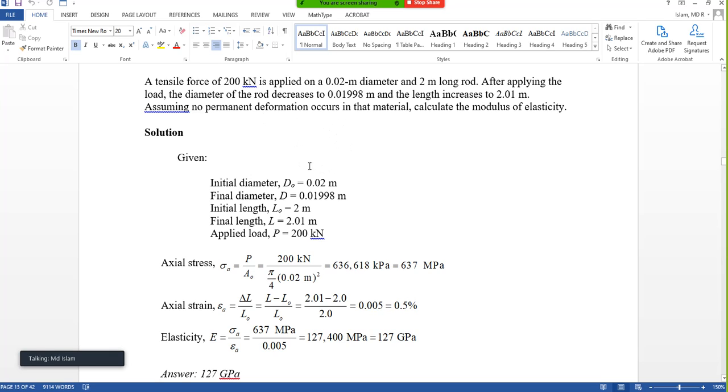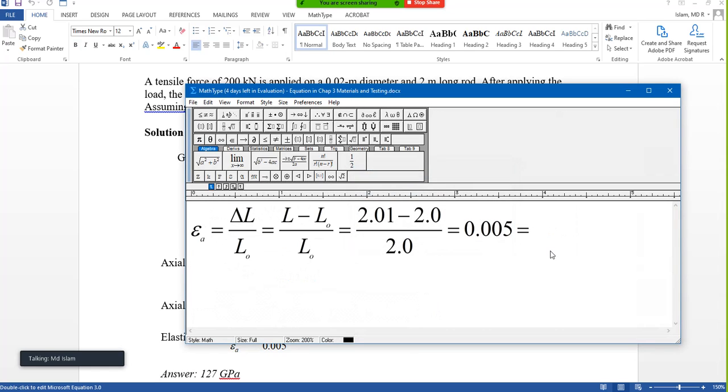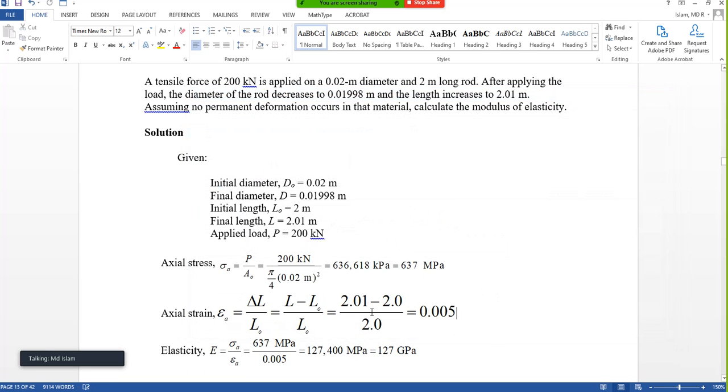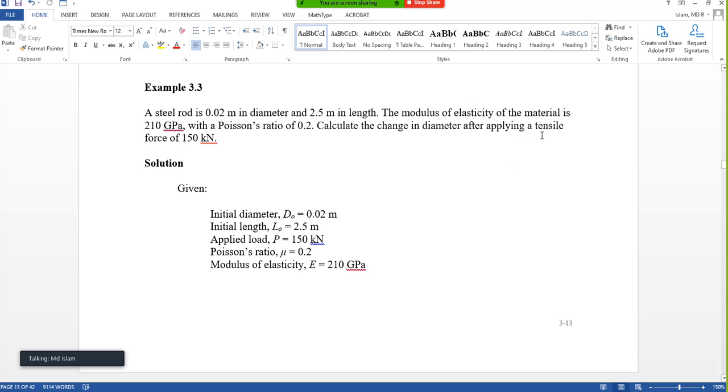Okay, so I do not need to explain this problem. It's very simple. Force divided by original area is stress. Change in deformation divided by original dimension is strain. You can take the fraction or you can take the percentage. Actually, for elasticity, you should take the fraction. I do not know why I used percentage here. Percentage was from when we used Poisson ratio at that time. I know why: when I solved that problem, I copied and pasted, and then it became that mistake.